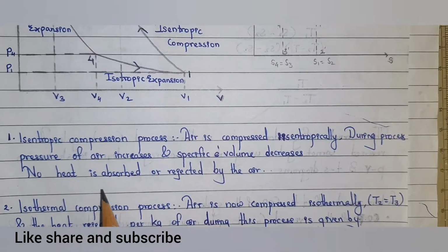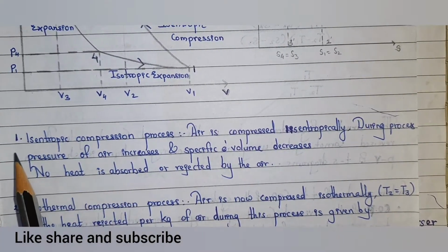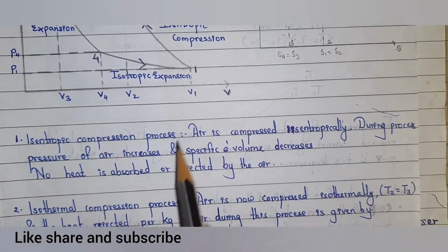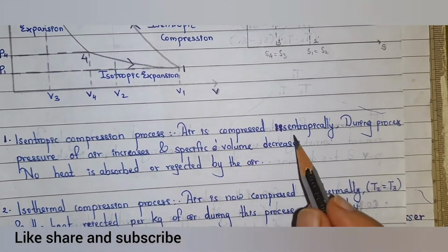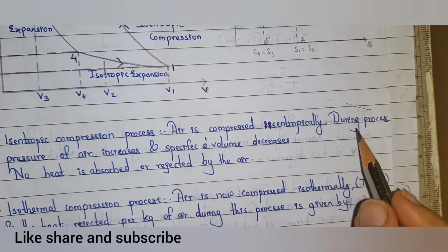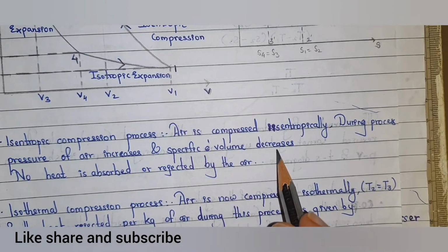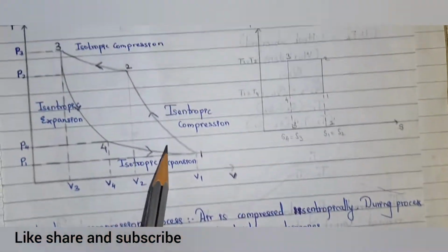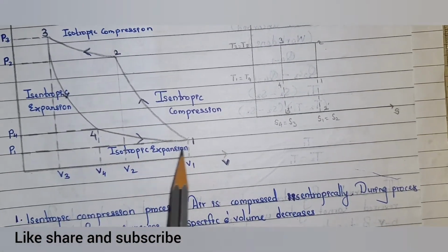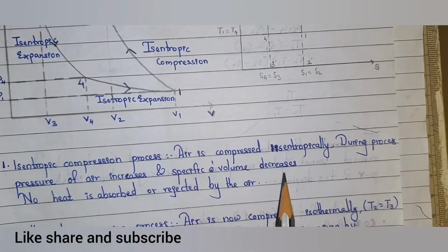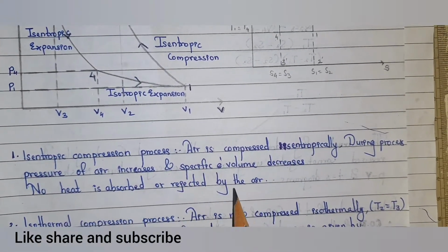Now the first process, how it takes place generally, is isentropic compression. Here air is compressed isentropically. During this process, the pressure of air increases and the specific volume decreases, as you can see in the figure. Here there is a rise in pressure and decrease in volume. Now here no heat is absorbed or rejected by the air.